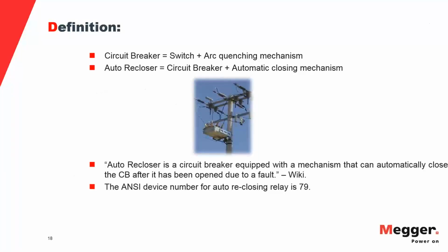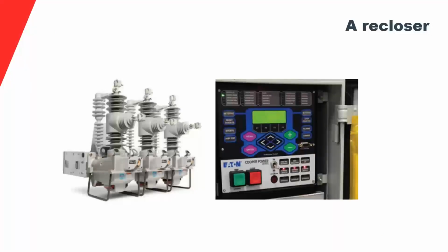Okay. Now, how do reclosers look in real life? Well, in real life, you have the breaker, which contains also the sensors that the reclosers have. Initially, reclosers, when they came to existence prior to World War II, were mainly overcurrent devices, and because of that, they only had current sensing capabilities, and they had no idea what the voltage was on the system.